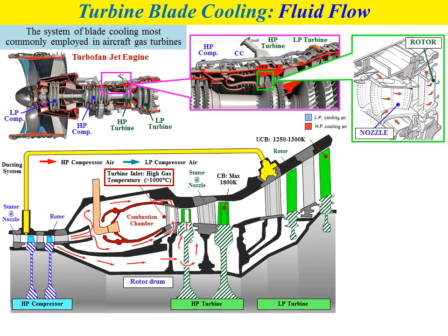Okay, for the second nozzle of the high pressure turbine, this nozzle will use two types of cooling air. First, the high pressure cooling air. The second one is low pressure cooling air. So this nozzle blade will have two types of passage. First, the passage for high pressure cooling air. The second one for the low pressure cooling air. As shown in the figure, the high pressure cooling air will enter from the bottom of the nozzle.